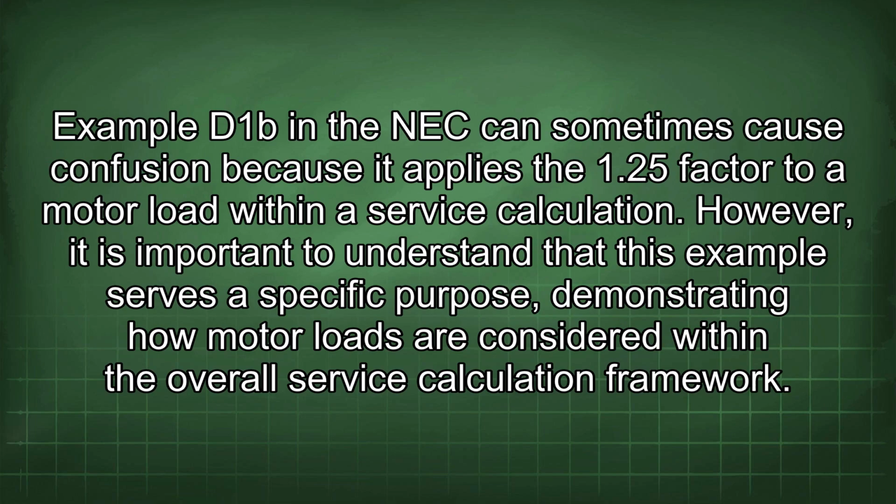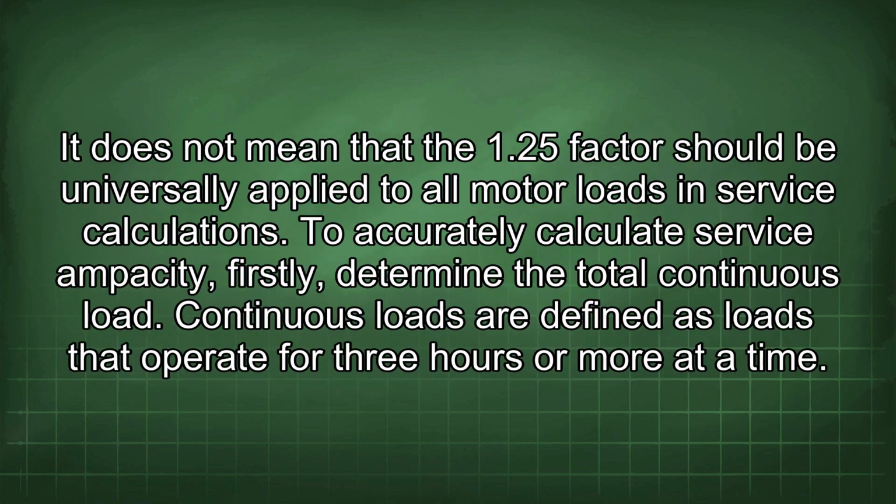Example D3 in the NEC can sometimes cause confusion because it applies the 1.25 factor to a motor load within a service calculation. However, it is important to understand that this example serves a specific purpose, demonstrating how motor loads are considered within the overall service calculation framework. It does not mean that the 1.25 factor should be universally applied to all motor loads in service calculations.